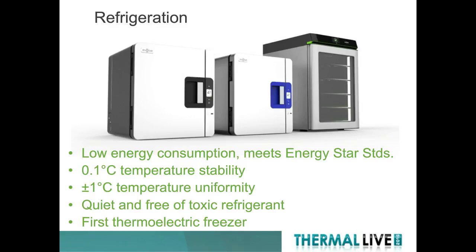So the biggest function of the refrigeration is the performance of the system. As performance requirements increase with respect to laboratory, scientific, or medical applications, the temperature uniformity within that chamber and the stability of that chamber becomes a critical factor to the acceptable performance levels. We've all had frozen celery and spoiled milk in our refrigerators because the energy requirements for residential refrigeration cause the uniformity within that chamber to be poor, which allows for large temperature differentials. In the medical space, that's not acceptable, and because of that, vapor compression systems have to work differently in order to be able to provide the stability and the uniformity required for those applications.